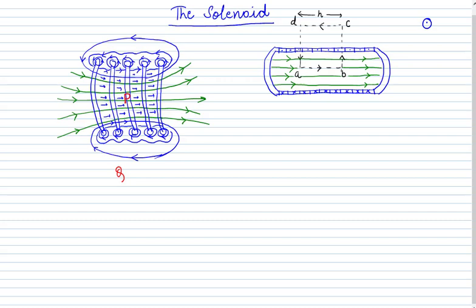So here in the upper part, I have used a dot which shows the direction of flow of the current. And if you go to the lower part of the loop, it is in the clockwise direction. Again, if you use the right hand thumb rule and fold your fingers in the clockwise direction, your thumb is pointing downward. So the current is flowing in the downward direction. I have shown it with a cross, because a cross always points into the plane of this sheet. So that shows the direction of current.